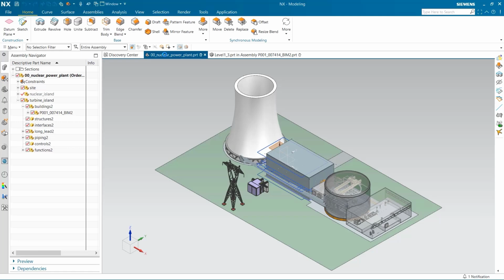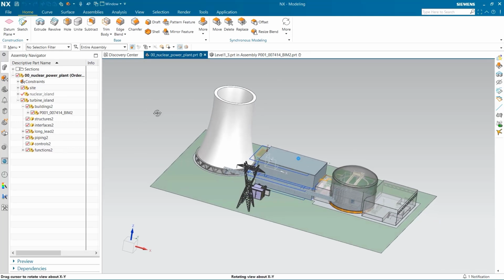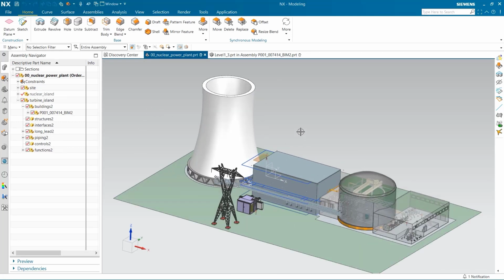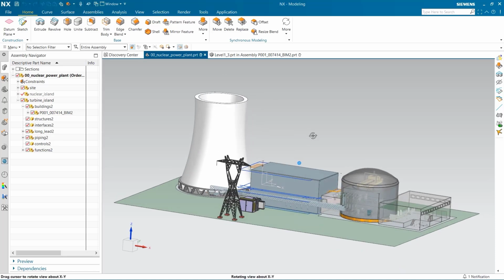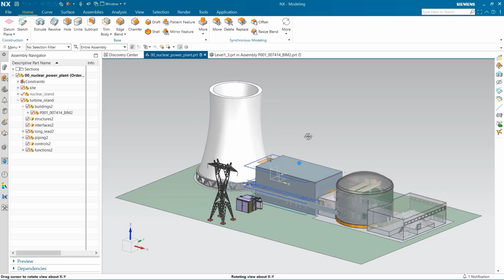You can see how easy it was to make a building using BIM. You saw me create levels of varying heights, and then make a sketch on the bottommost one. You saw me build walls referencing this sketch, and I then made interior walls using grid.